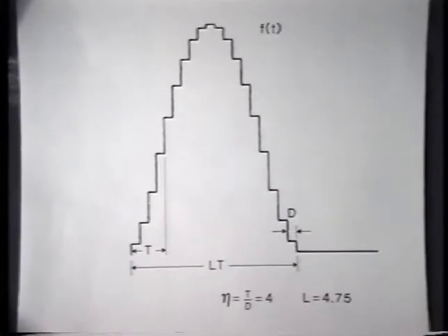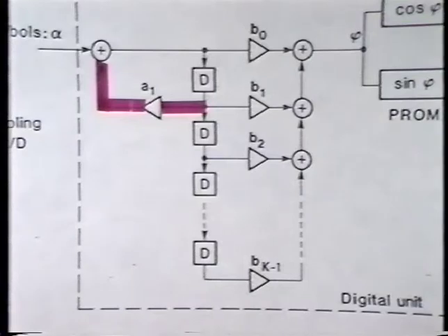These are the unit filtered pulses, which last for 4.7 symbol intervals. The staircase function is generated by oversampling at 4 times the symbol duration. This emphasizes the digital integrator which has been removed in our implementation. In an FM system, A1 is 1. In our implementation, A1 is 0.